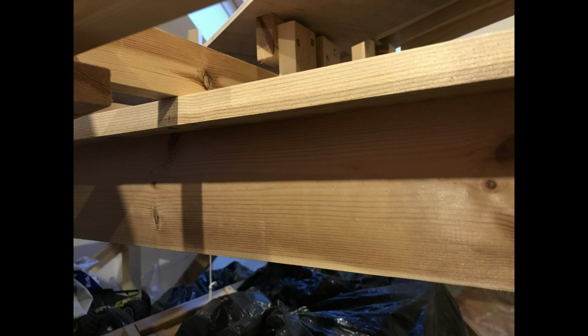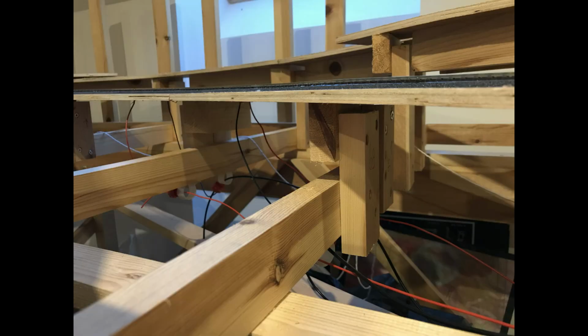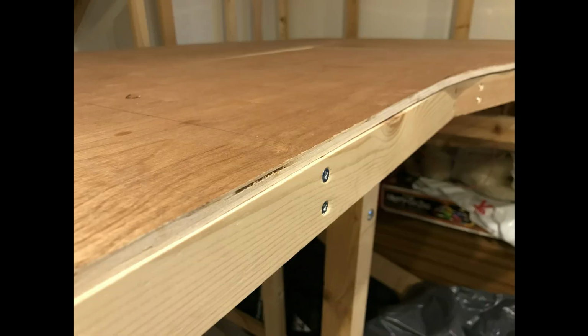L girders were made up from 4 inch by 1 inch and 2 inch by 1 inch timbers combined, and the joists, risers and cleats all made from 2 by 1 timber. Track bed is 9mm ply. One of the mistakes I've made is not using the best quality plywood. It seemed okay at first, but I've had problems with poor quality laminations and gluing in the ply.